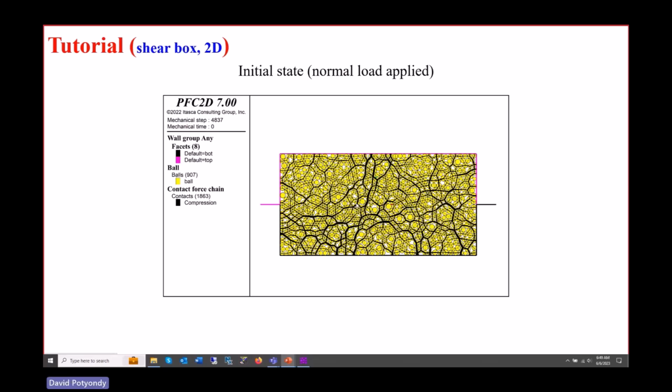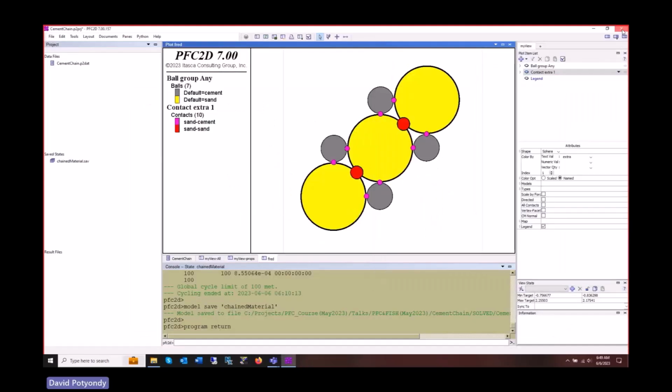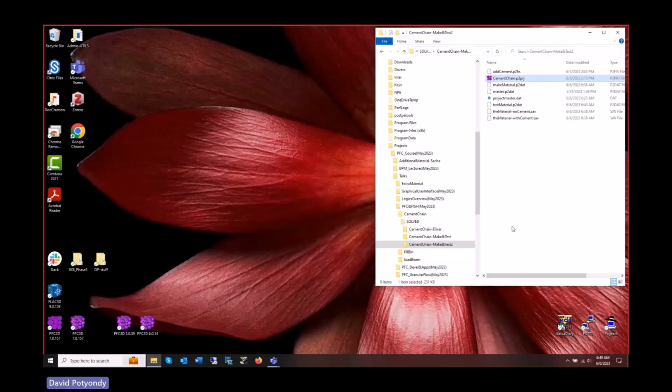And then the last thing, sometimes people then also, as we'll see, we have the ability to build a bonded system and to put in a joint that goes across these things, and we can use a special contact model there so that that bumpiness is removed, and we can control the properties of that joint. So people might make this a bonded system, put a joint across, and now do a shear box test on a rock joint, right? And so that's another thing that people would often do with something like this. Okay. So we've now concluded what we're doing related to fish.